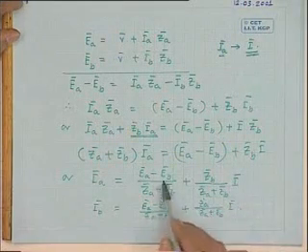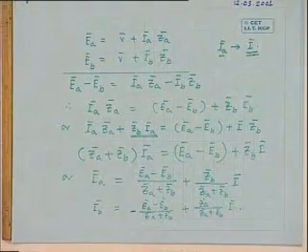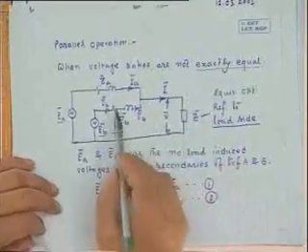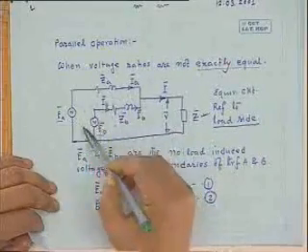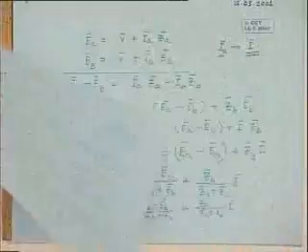That is, when the load current is 0, it will be the circulating current. Because when this circuit is opened, I bar is 0, IA bar and IB bar will be equal and opposite in nature, and the current will circulate inside the secondaries.